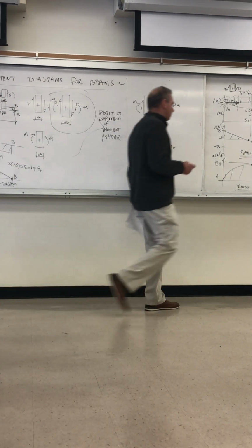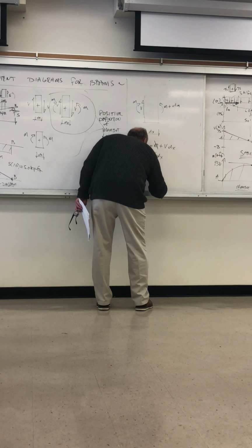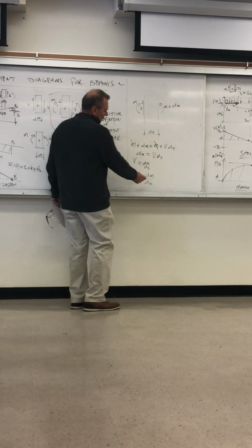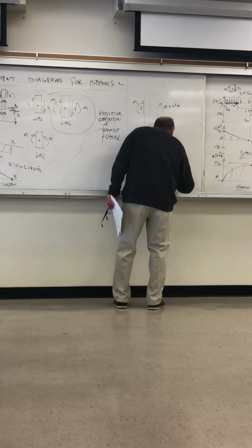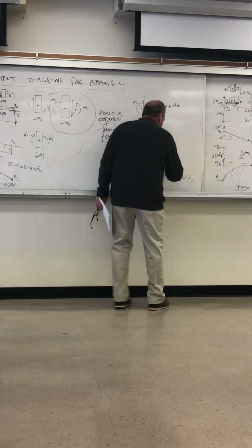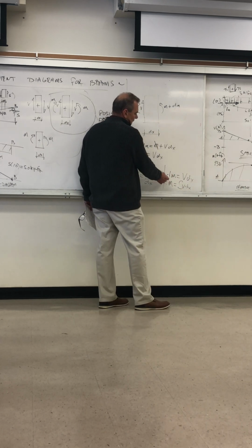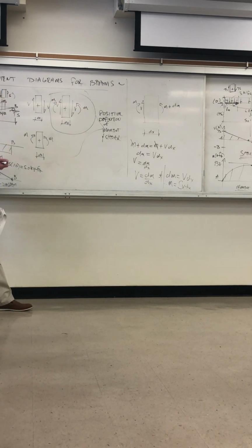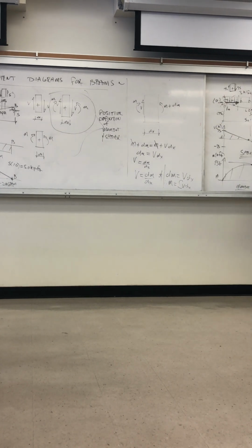So let's go look at this one a little better. Or we can look at both of them. So this is saying there are two things. V is dM/dx, the differential of the moment diagram with respect to x, so it's the slope of the moment diagram. But you can also take dx to the other side: dM is V dx. I'm just taking the differential dx to the left side of that equation. And therefore M, the moment expression, is just the integral of V dx. You integrate both sides of that, that becomes M. So the moment is the integral of the shear expression. The shear is the slope of the moment diagram. They're interrelated, just like in differential calculus and integral calculus, where you can integrate and differentiate functions.